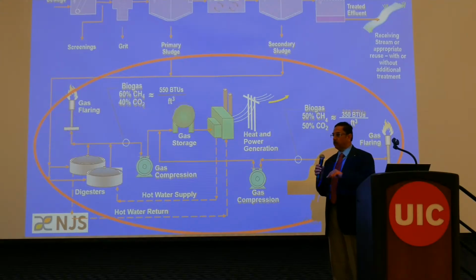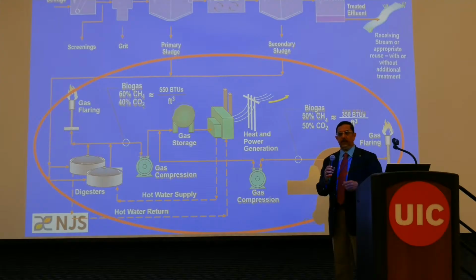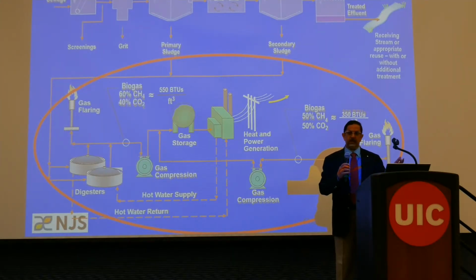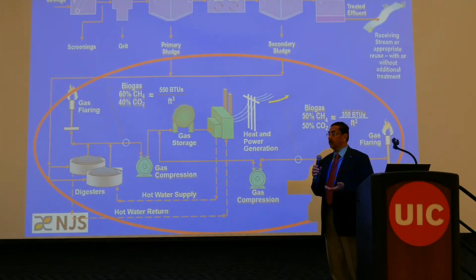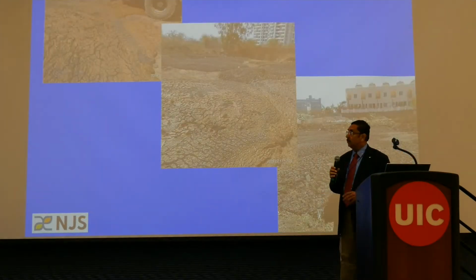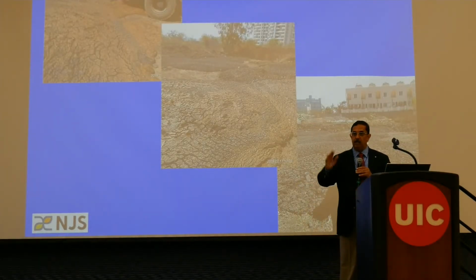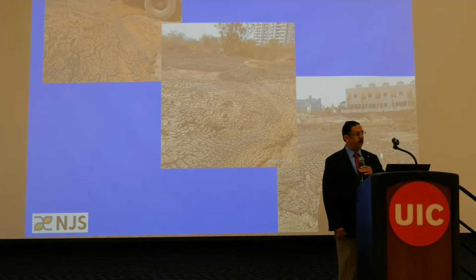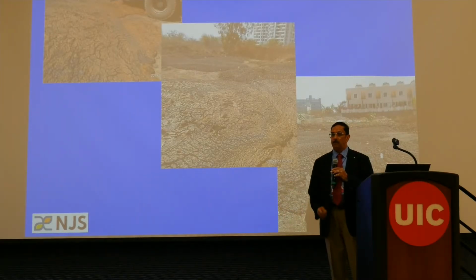In order to look at what regulation should be brought in and how we can use this wastewater sludge that is being generated at a particular site, for example, the capital, which generates somewhere around 230 to 250 dry tons per day. Presently it is simply discharged at 20% or 18% solids onto the land, which is not hygienic, and it reaches the rivers, and you will have more pollution coming down the pipe.